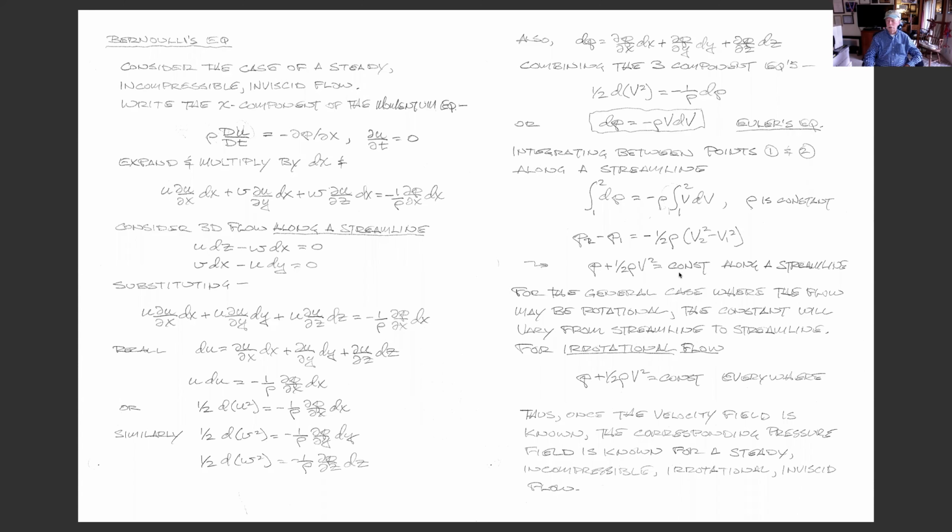But Prandtl showed that this boundary layer is confined to a thin region, its depth is not very deep, and so at the edge of the boundary layer, you can assume the velocity is the potential flow velocity. If we have a streamlined body, we can, in essence, ignore the boundary layer.